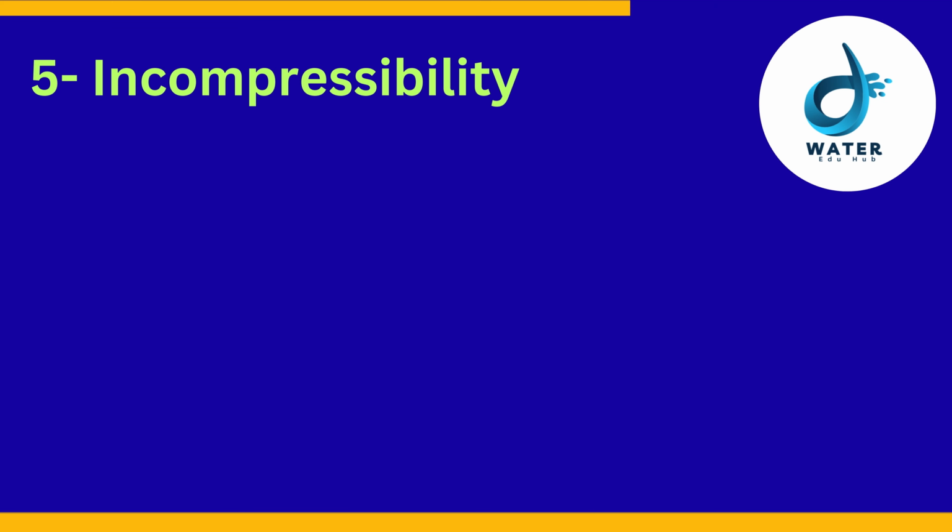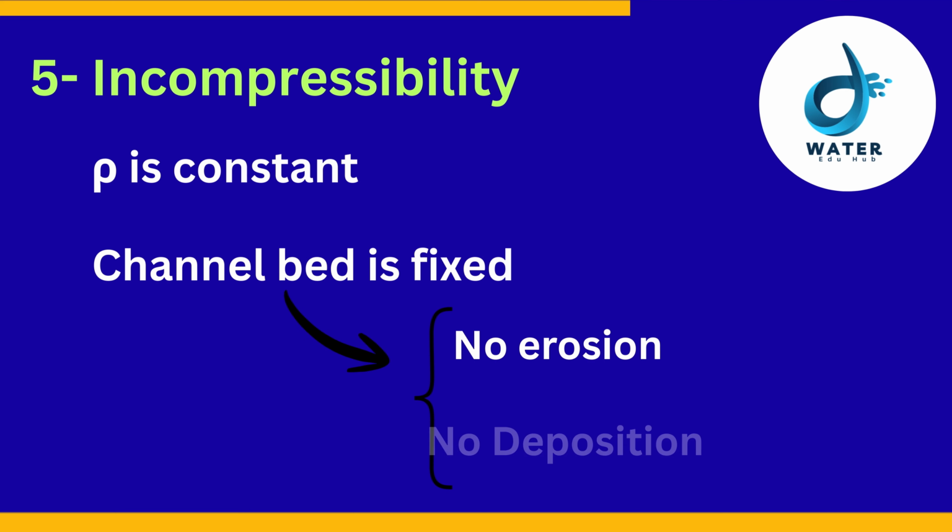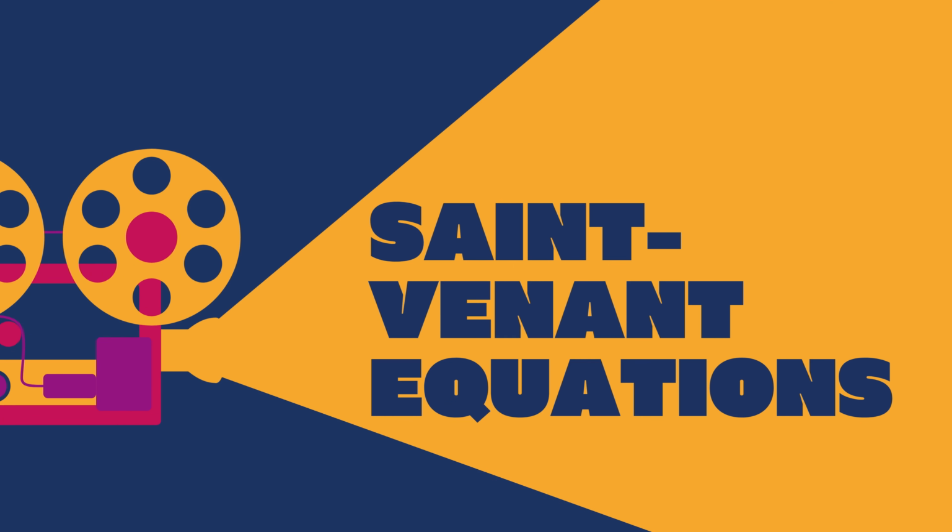The last one is incompressibility. The density of water ρ is presumed constant, and the channel bed is also assumed to be fixed. Therefore, no erosion or deposition is modeled in the pure hydraulic equations. Now let's explore the Saint-Venant equations.